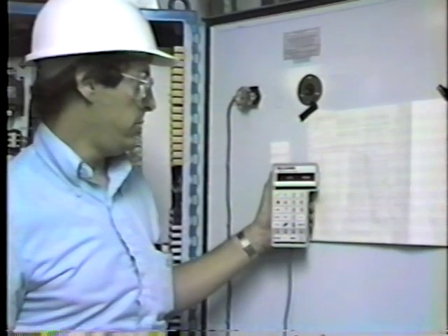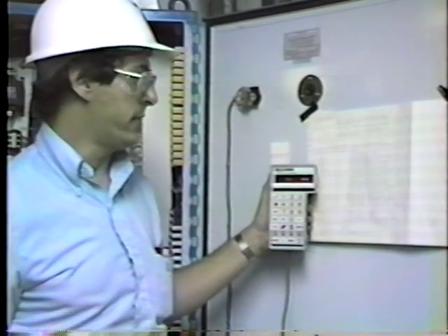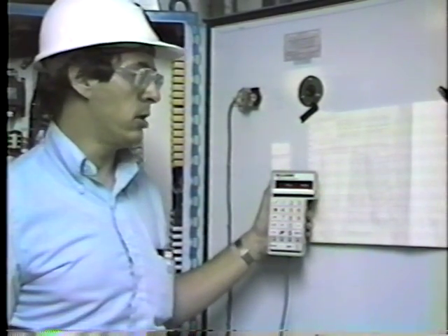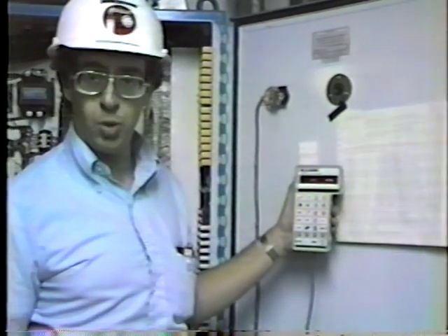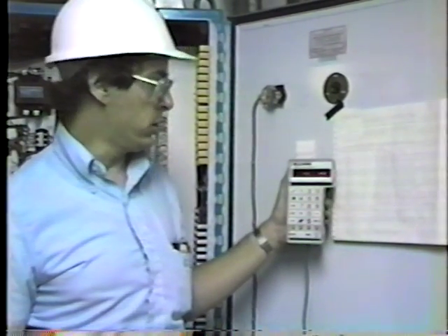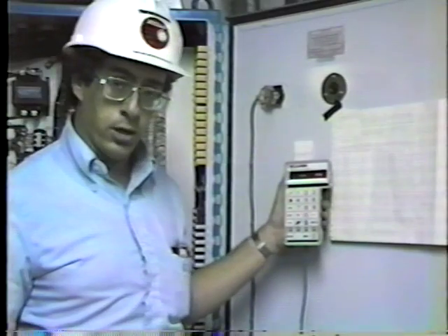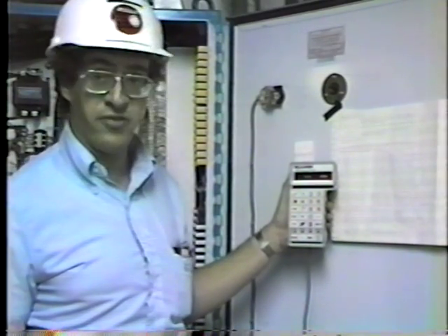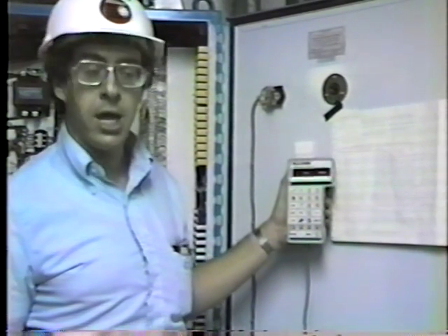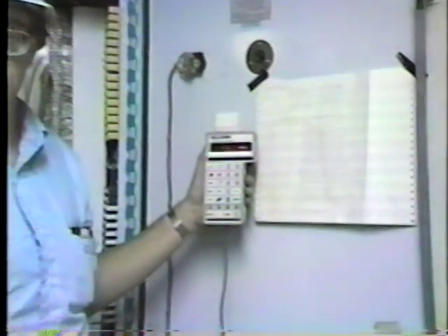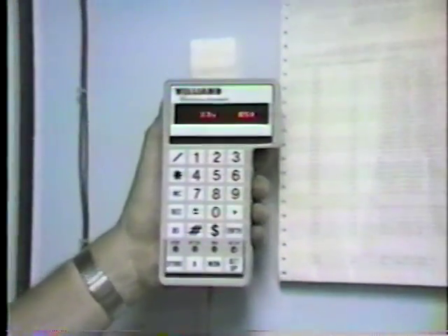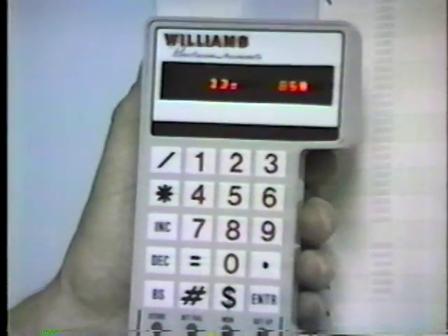Number 13 is the feeder conversion factor. This is the factor that we calculated boiler demand, and then we multiply the boiler demand by the linearizing factor of 85%, and that goes out as our feeder command. Okay, that's set at 85. All right, 14.